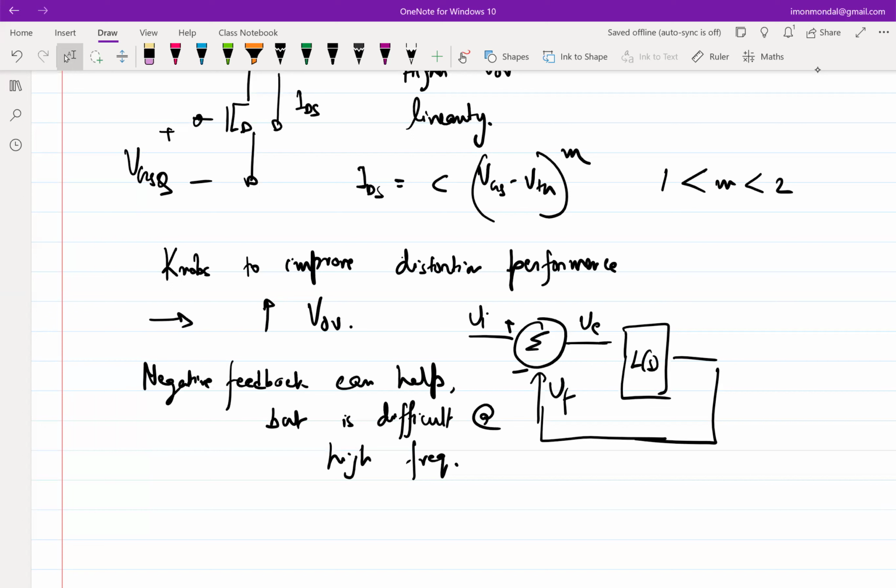60-degree phase margin, 70-degree phase margin, no issues with instability. But let's say you have decent enough gain at 2 gigahertz. The loop gain, let's say, is 20 dB, but the phase lag is also some 90-degree phase lag. 90 degree is not correct. So let's say 60-degree phase lag from wherever you started, right?